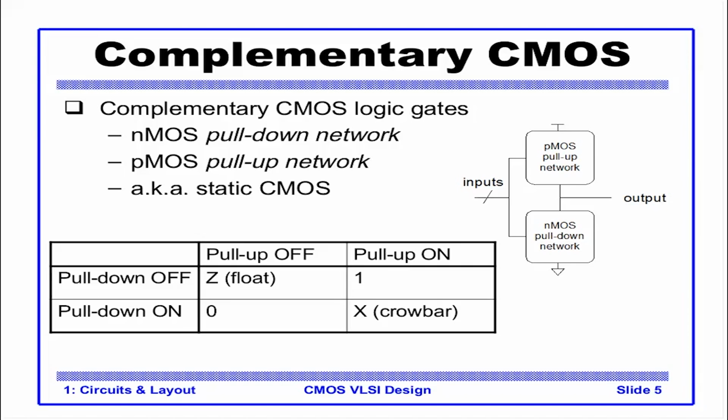Similarly, when it is connected to ground via NMOS, it is sinking a very negligible amount of current. What this means is that this kind of circuit is very power efficient. When we see different logic styles in later chapters, please try and differentiate between this logic style and other logic styles on the basis of power.